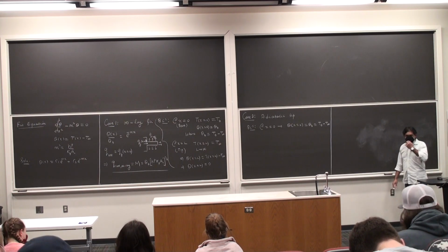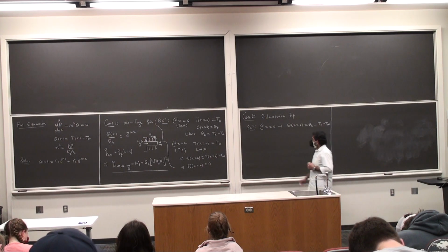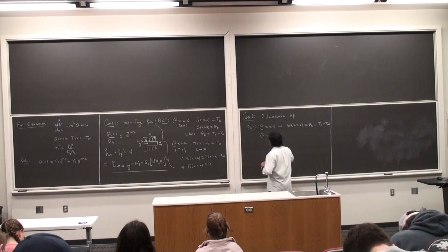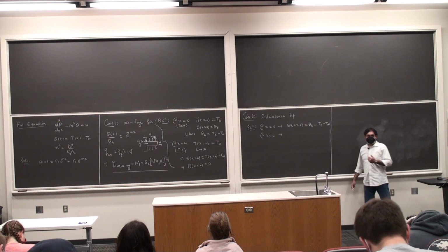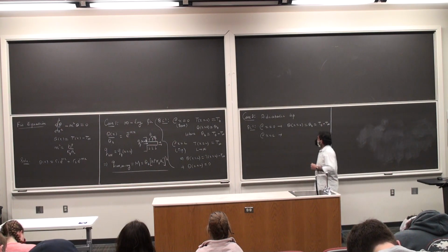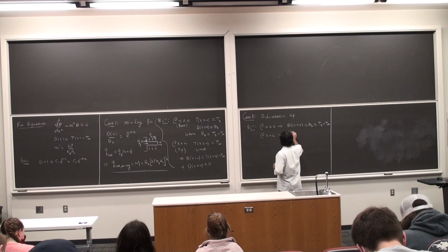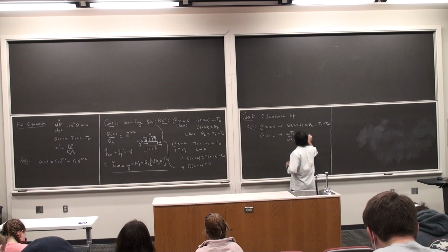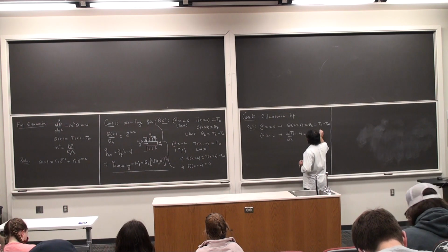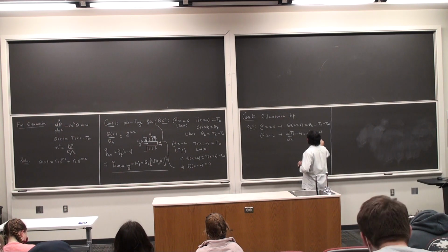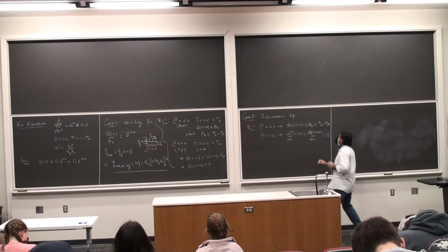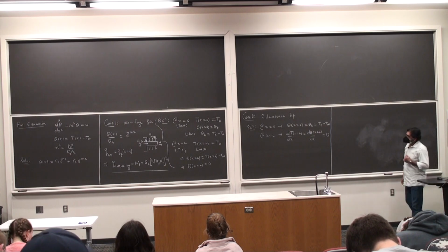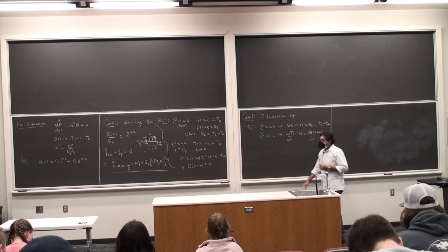Okay, and then at x is equal to L, we have the convection boundary condition, but there is no heat transfer. The tip is adiabatic, so the conductive flux is 0, or dT by dx is 0. So the temperature gradient is 0. If the gradient is 0, it means that the slope is 0. It's an adiabatic condition.